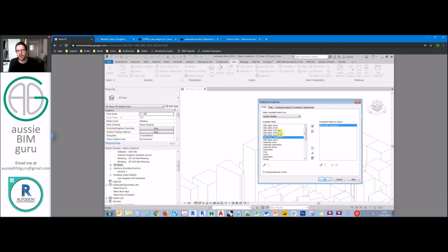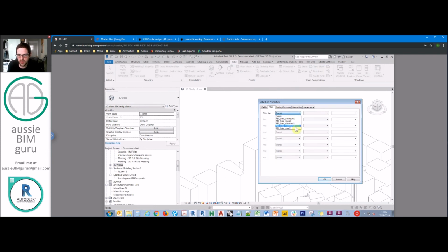And you'll recall that we made a count parameter back in the last part, 2 parts ago, in our sensor family. So we're going to use this instead of the actual inbuilt count parameter, because this lets us use it in formulas. So we're going to add that one as well, and we'll add comment 1 and comment 2, and probably area 2 as well, which is the overall controlled area of that sensor. So we're going to filter by comment 2. We'll do comment 1 first actually. So we'll do comment 1 equals option 1b, and comment 2 needs to contain the word tower.